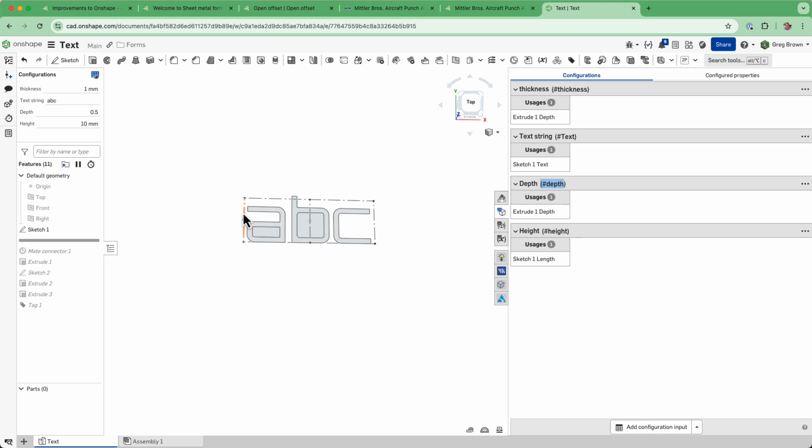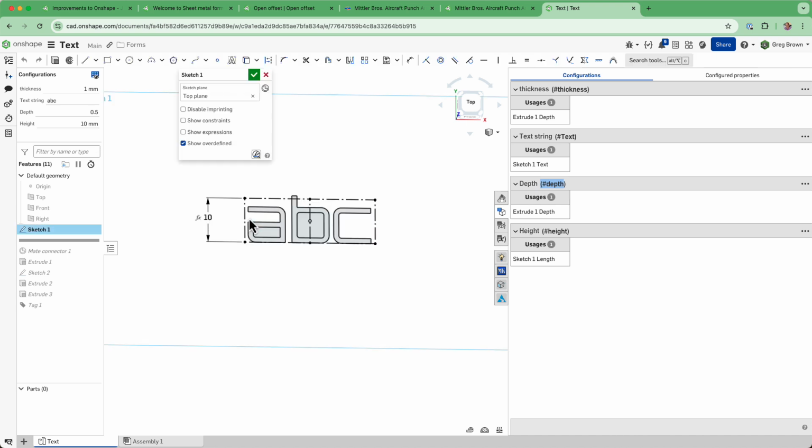So if we edit this sketch, you'll see that I've used that variable height. It's handy as you just roll over the mouse, you can see the expression being used, just height. The other thing I have done in here, which is interesting, is if I edit the actual text, you'll see something kind of special and crazy you may not have come across in the past.